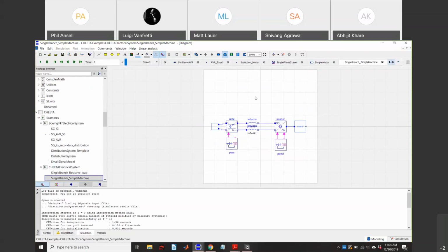Okay? So the PWMs are driving the switching process of the power electronics, is that right? Exactly. And it requires some sort of control functionality on top. So right now we don't have that. The control functionality that you need on top of this is a DC voltage controller that would be controlling the voltage on the DC side where we're connecting to the inductors, because the fuel cell voltage is going to be controlled internally by another subsystem.